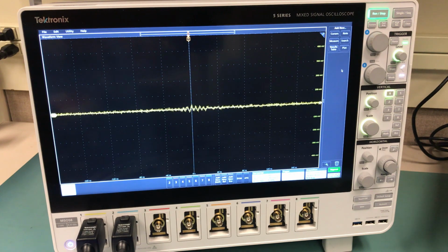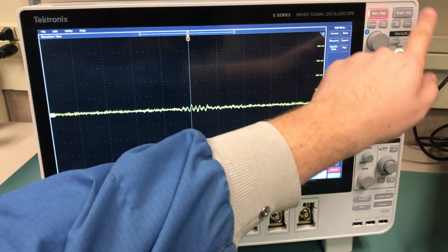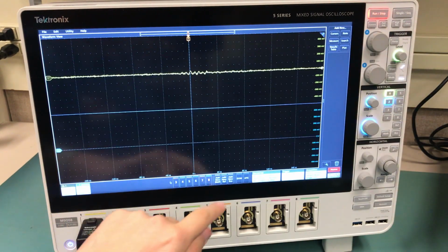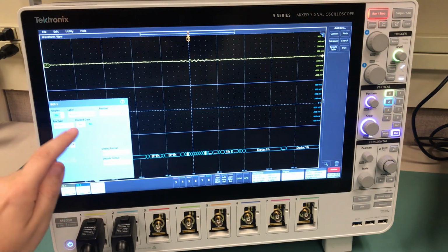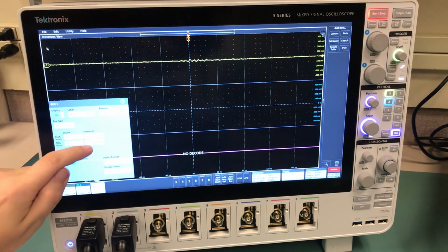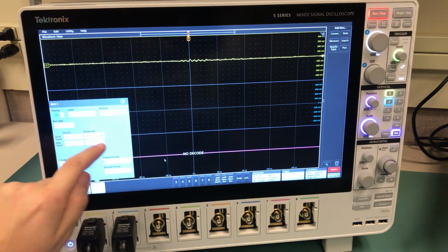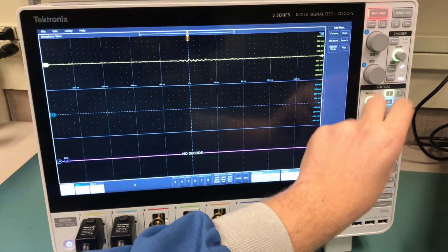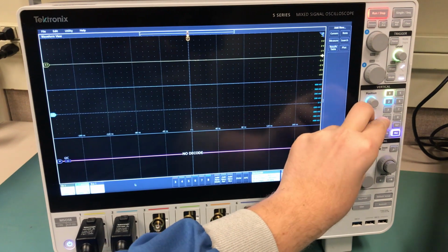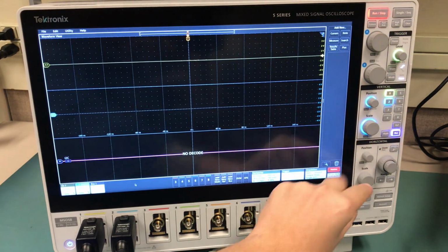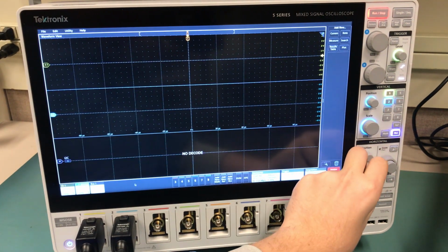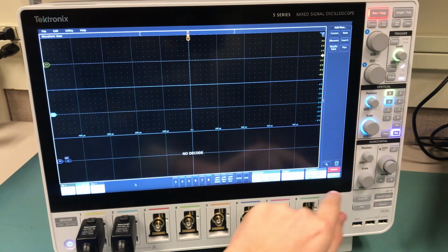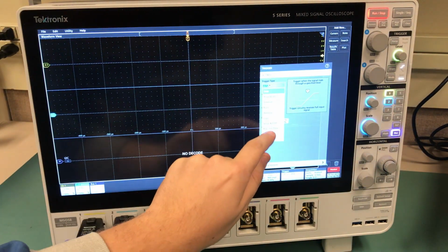This time, we're going to configure the MSO to decode the I2C bus, but we're also going to use the advanced triggering capabilities of the MSO to trigger on the bus's opening declaration that only happens when the bus first starts up. You can see me setting everything up from default settings in this fast-forwarded footage. One key feature we're going to use is called Fast Frame. It will allow us to capture multiple full trigger events on the scope, then cycle through them at our leisure.